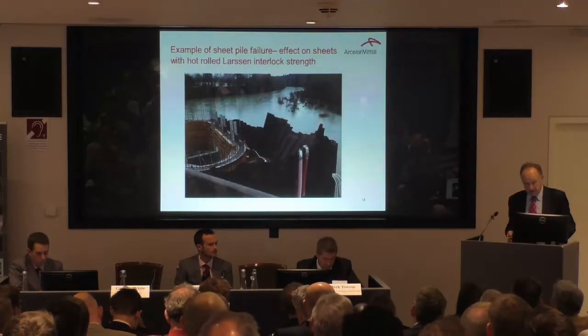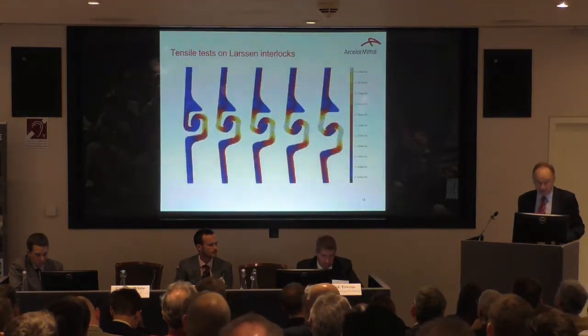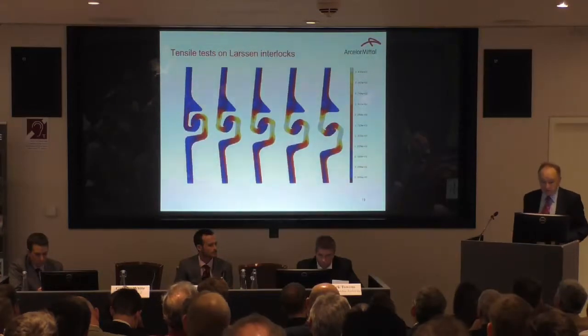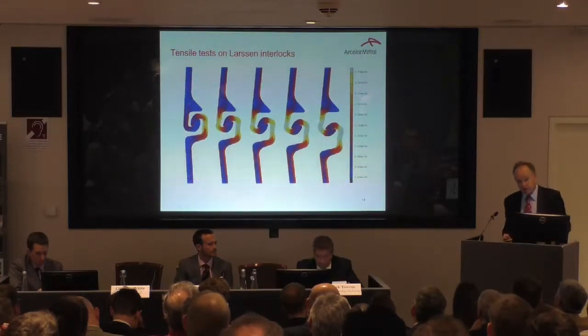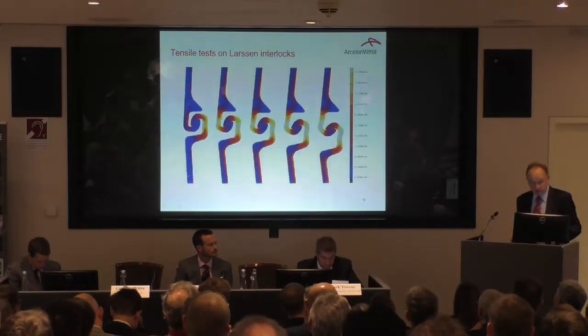They actually stay connected together because for these sort of structures you should be looking at hot rolled interlocks to EN 10248. These have been tried and tested over 80 to 100 years and are well proven to take high load.